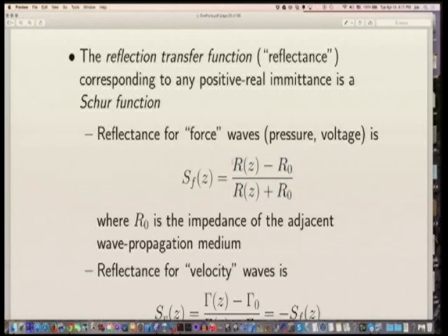The way I think of it is the impedance step over the impedance sum. It's how much you jump up divided by the sum. And intuitively, imagine you hit a brick wall. The impedance is infinite. Well then, these terms are dominating. R0 is small and finite, so you just get 1. Your reflectance is 1. Does that make sense? Yes, because we're talking about force waves. Force waves will reflect without an inversion.